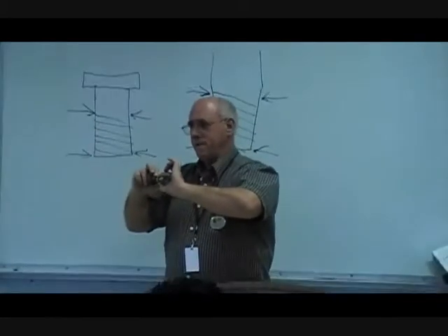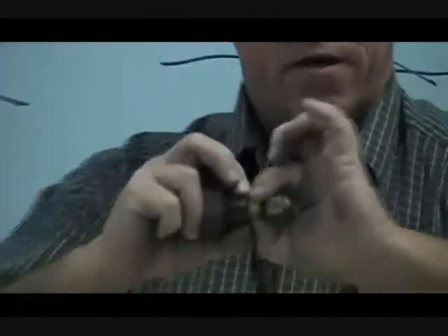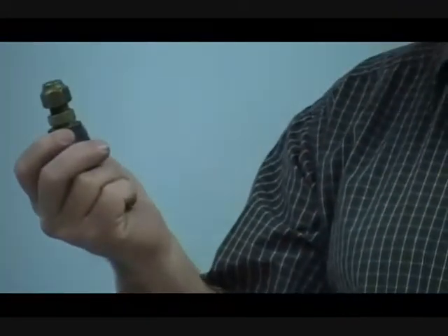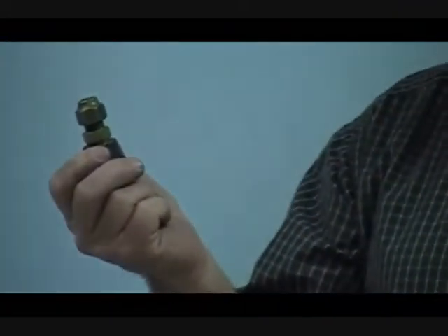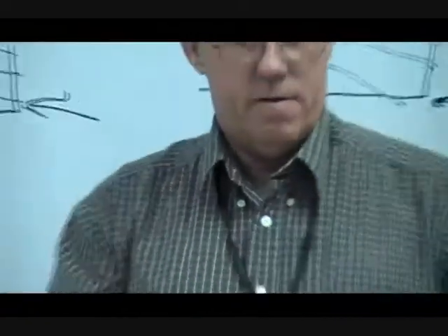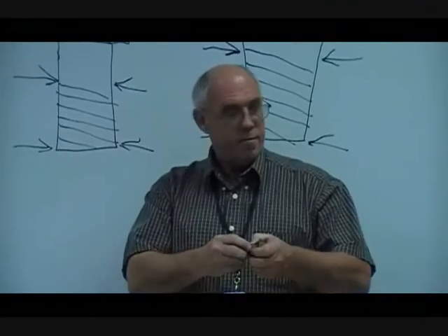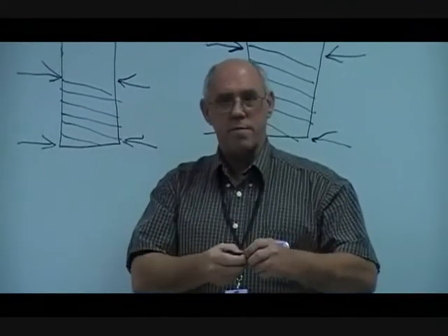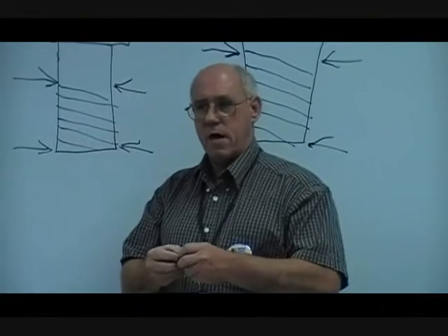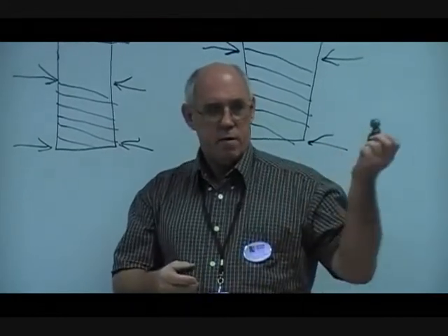Okay? But it don't fit. It's loose. It's not made for one another. Now you would think somebody piping up in the field would know that, right? I've seen this done. Now if you got natural gas coming through here, you may say, okay, well, they put pipe sealing compound on it, but that pipe sealing compound is not going to stay. It will leak.